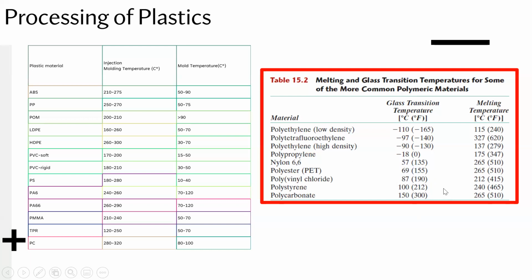So what is the perfect place to do processing? If we choose somewhere in between here, you can deform it to some level, but not as freely as you want to. And when I say you want to, you'll see in the next couple of slides some of the most common manufacturing processes, how you actually need the material to be molten and liquid. Although you can deform it to some extent here, you typically want to go beyond the melt temperature.